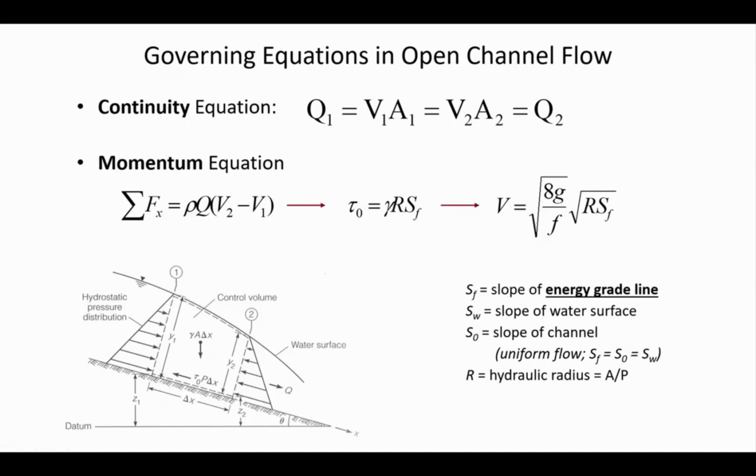And so there can't be any accumulation here if we have steady flow. So if this is non-uniform but steady, that means that the depth is constant over time, then that means that A1 V1 has to equal A2 V2. So even though maybe the velocity is faster at 2, the flow rate is the same because the depth is less. Okay, so continuity will be one of the tools we use this semester, and then the other is different equations that are derived from the momentum equation.